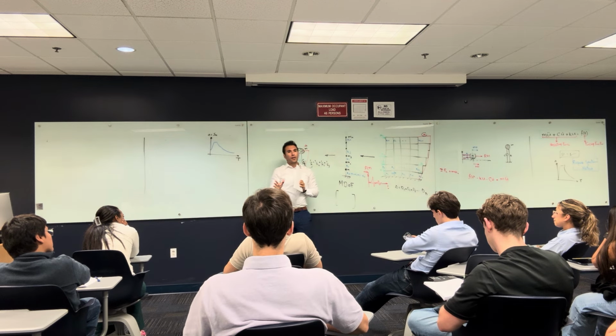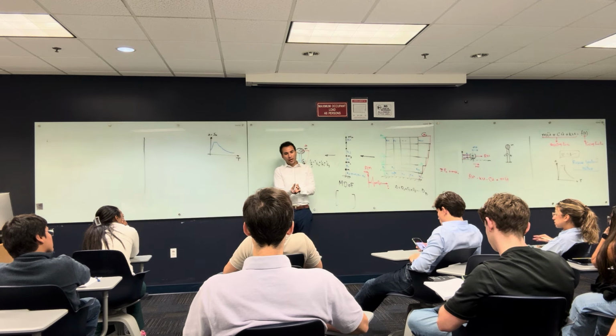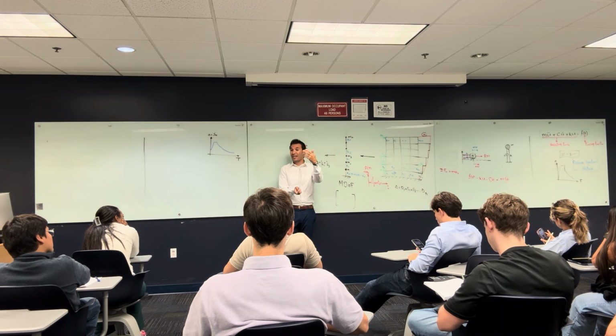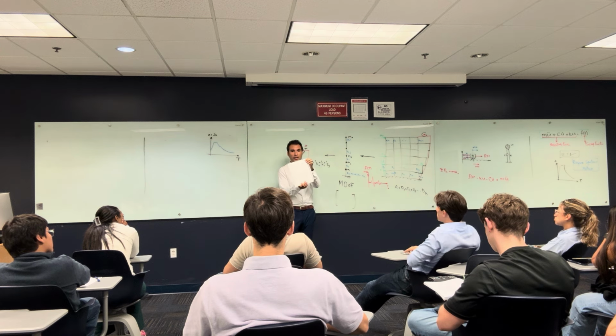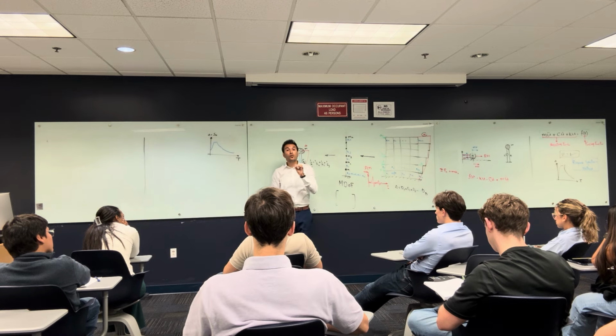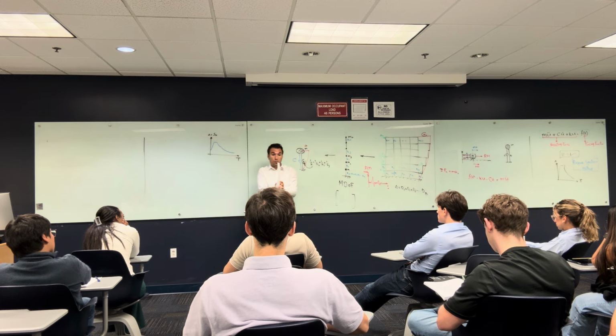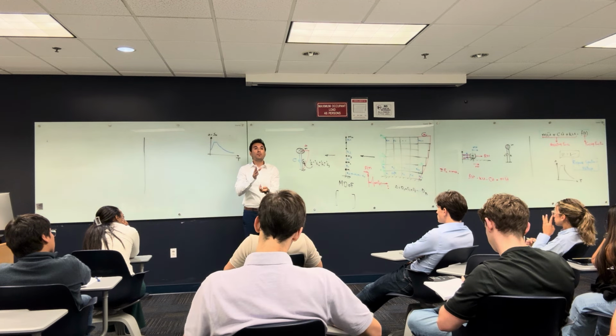But the thing is, you should ask me a very, very fundamental question. What is it? But what if my structure is gonna move the other way? It's gonna have a different period. Like, your structure is gonna move that way. So it's still the time that your structure is gonna take to go this way and come back to the original place. What if your structure is gonna have torsion? Same thing. The time that your structure is gonna take to make this and come back to the original place. So that means that your building has multiple periods. Depends on what? Depends on how the movement looks like. And this is actually depending on the mode shape of the structure.